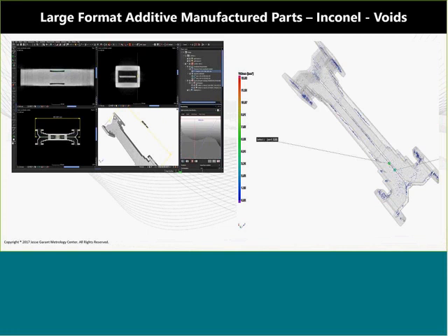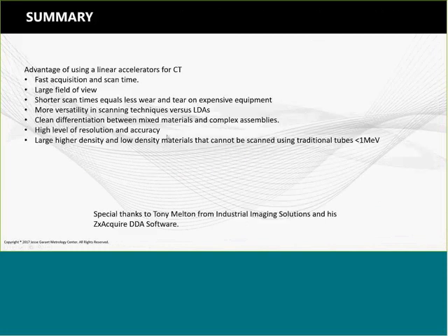But if you want to actually see meaningful results, i.e., within 200 micron, 250 micron, then CT is really your answer, because in a single data set it will capture not only voids, but wall thickness measurements, inclusions, structural analysis, fiber analysis. Every type of analysis can be run off a single CT data set after capturing.